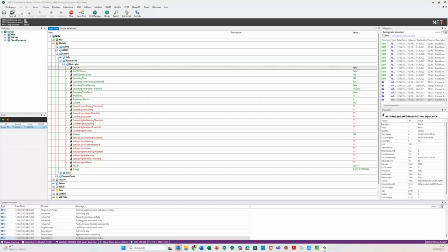And about the last question, Alexander, if I knew it, I could not tell you if it's not ABB. So I'm sorry for this, but telling you the truth, I don't know. I don't know which manufacturers are planning to include it, but I guess all. But this is not easy and fast to do because it has to be information coming from the drivers, from the ballasts. The ballast has to be ready for this energy consumption acquisition. So if the ballast is not ready, it doesn't matter the software. We will get no info.